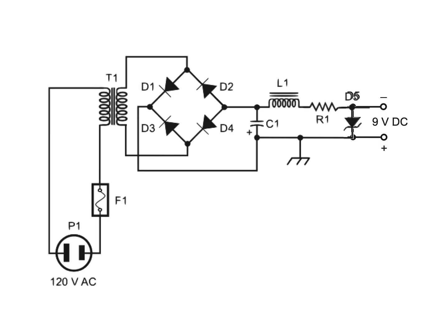This slide shows a power supply that will do a good job of providing a constant, pure, 9 volts DC. It's just about the same circuit as the one you saw before. The basic component layout is the same, except that all the diodes go in the opposite direction as compared to the one you saw before, including the Zener diode, and the electrolytic capacitor polarity is reversed. And of course, the voltage of the power supply shown here is lower.